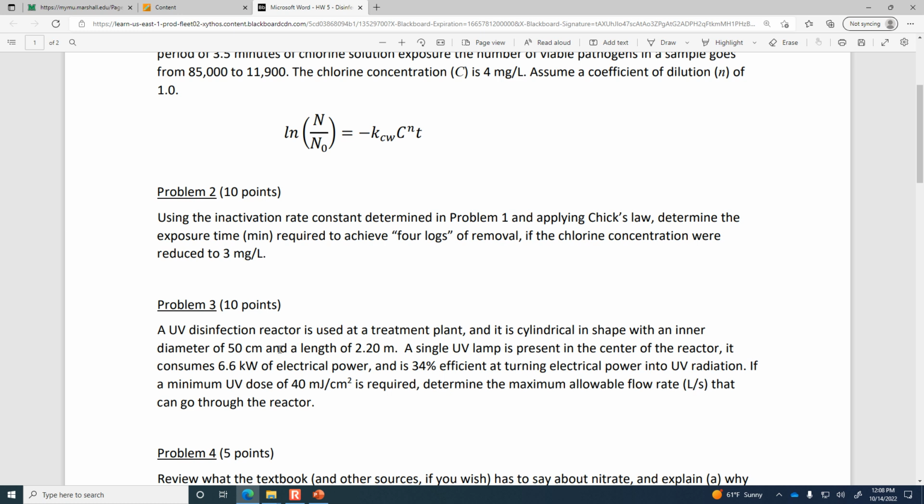Just the difference is that now you're having to calculate the amount of time the water should spend in the reactor, because a joule is a watt second. And so you'll figure out how much time the water needs to spend in the reactor, and then given the reactor's volume, you can calculate the flow rate that should go through it, because flow rate Q, of course, is volume per time. And so we know the reactor volume because we have its dimensions.